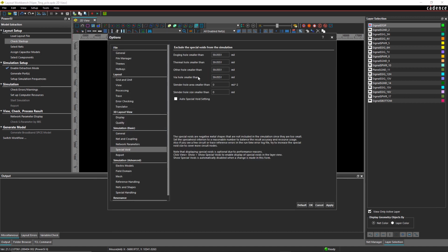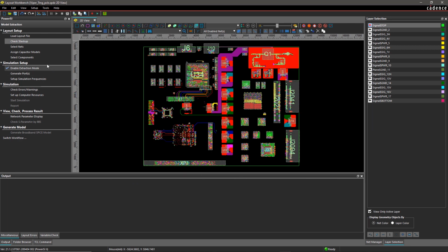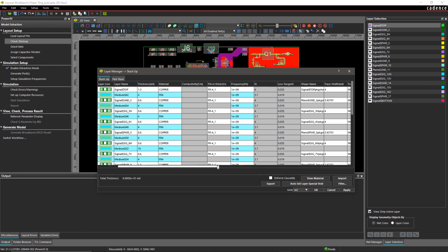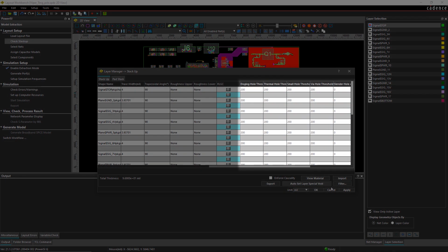When a signal travels across the reference plane, it passes through a gap or void. Electromagnetic effects of these voids are accountable above a threshold value. Defining void settings gives you more accurate results with respect to power integrity.